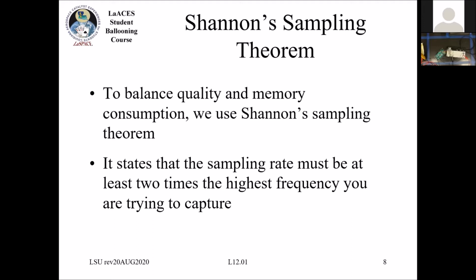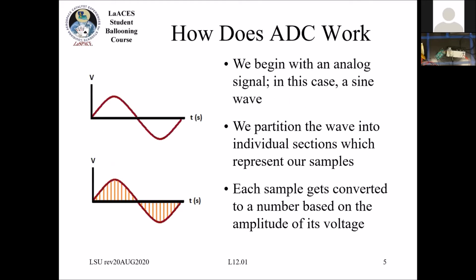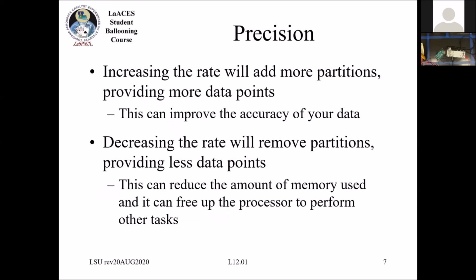In particular, if you have something that's oscillating between like a positive and negative value, right? Like our sine wave back here, I want to make sure I can see that it's going positive and negative. Because if my sampling rate is only at these 0 crossing points, I won't be able to tell the difference between something like this where it's actually oscillating positive and negative, or something that is just straight negative or straight 0 the entire time. So that's why you double it.